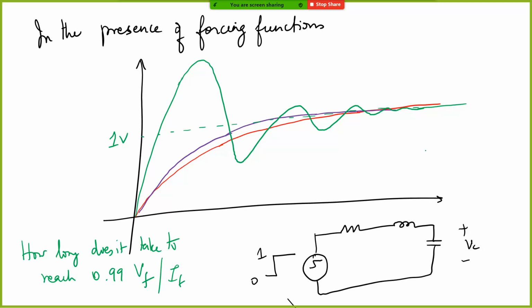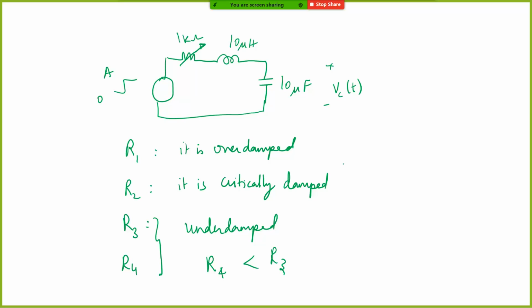So when you have a system and you give a sudden jerk to it, this can be a mechanical system or an electrical system. For example, it can be a suspension system of an automobile. It can also be that you have digital signals coming in and you suddenly turn on the power to an analog circuit, or you give a digital 1-0 signal to an analog circuit or a routing network, and how does it behave? How long does it take to settle?